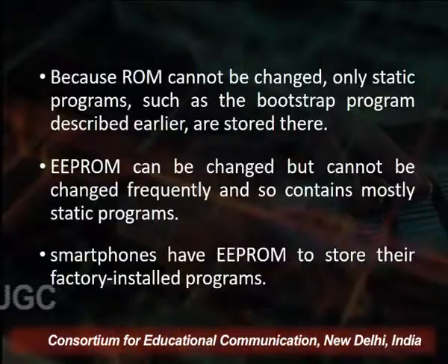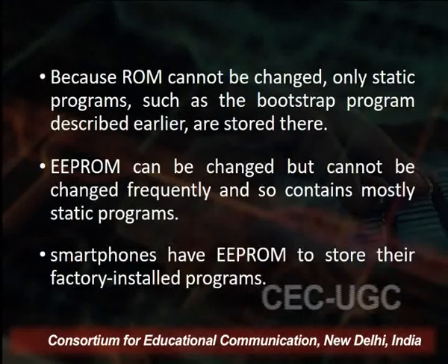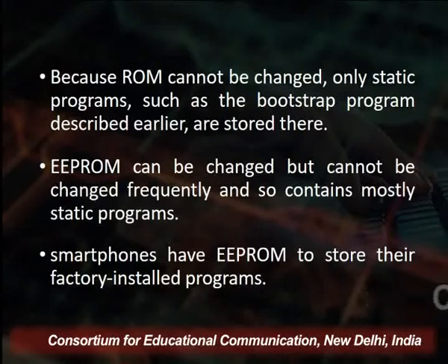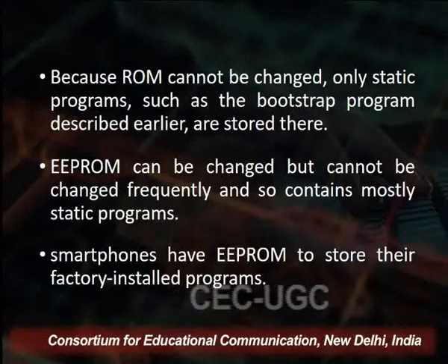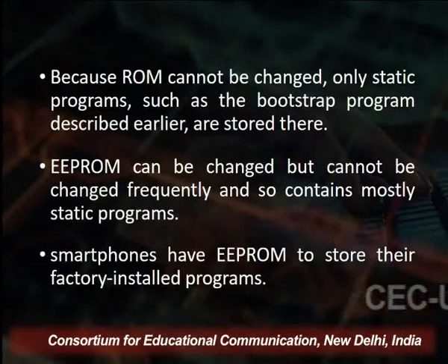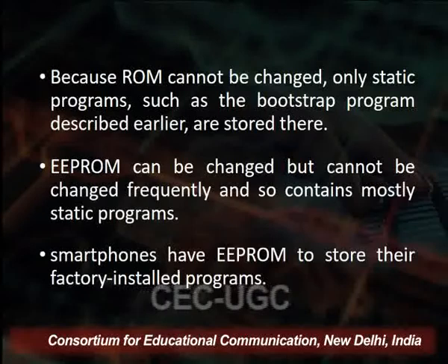Also, as part of firmware, we have EEPROM, which is electrically erasable programmable read-only memory that can be changed. Yes, it is not very convenient to change, or it cannot be changed very frequently, because it is electrically erasable and you need a special setup for erasing its contents. So this also contains mostly static programs. Taking a common example of a smartphone, the EEPROM in the smartphone is there to store the factory installed program.